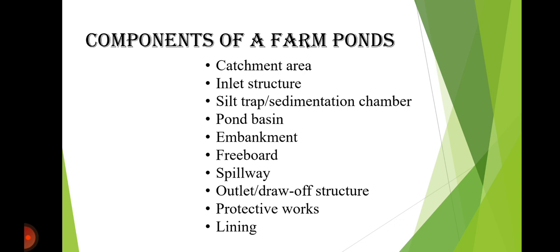So the next is protective works. Protective works includes the turfing or grass cover on embankment, stone pitching, fencing around the pond. Some of the functions of the protective work are to prevent erosion of embankment, and improve safety and durability. These are the protective work.